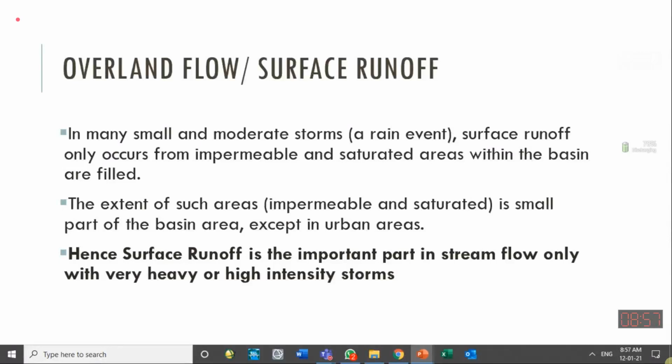What will be the effect? It will increase the flood level. It will reduce the recharge on the ground. That is happening in Lahore. Most of the area is now covered with concrete, bitumen, or steel surfaces. So most of the precipitation reaches the channels and enhances the flood peaks, and it does not go into the ground, so recharge is less and our groundwater is going down. So urbanization is affecting us twice.